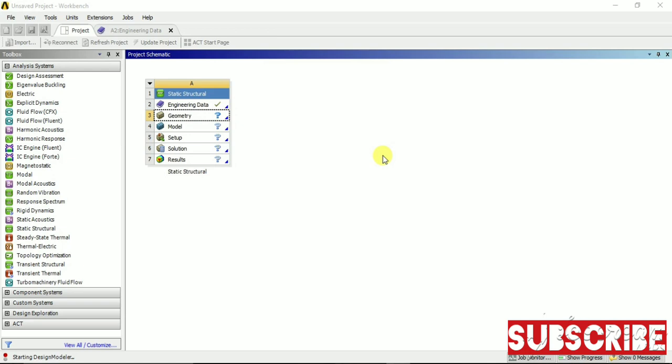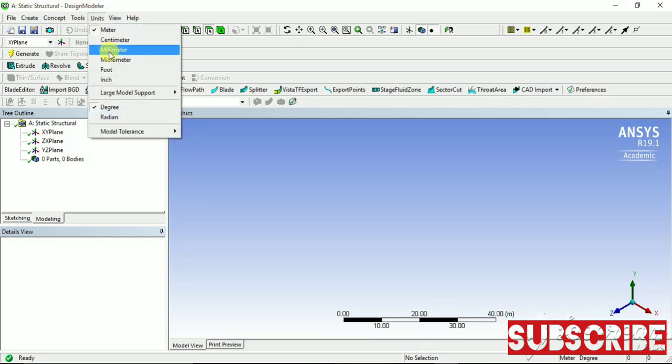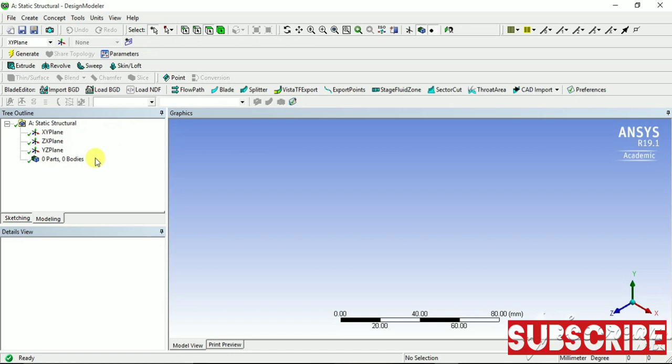You can import different geometry from other software like SolidWorks and CATIA, but if the geometry is quite simple, you should make it in ANSYS itself, as it will be better for the analysis. You can have good control over it if it is made in ANSYS itself. Take the units as millimeter.